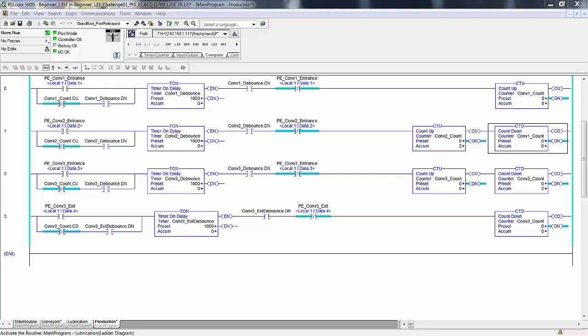Now, what are some of the things that you can do with the instruction set to go from instantaneous decisions, logic, to logic that includes time and space? With just a photo eye, can the controller know how many cartons are on each conveyor? No. How many cartons can a photo eye see? 1. If there are no photo eyes sensing cartons, does that indicate that there are no cartons on the conveyor? No. You could push a carton onto a conveyor and stop after a delay, using a timer instruction. Or, more deterministically, you could stop after the PE is clear of the carton.